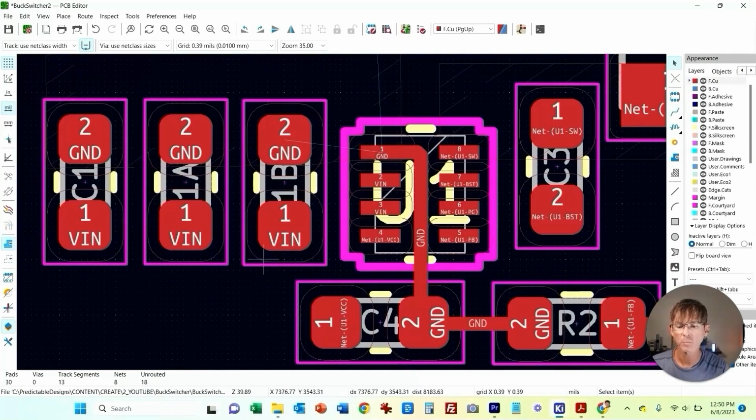Okay, now we just need to place our last copper pour for the VIN, which is going to grab the 3 input capacitors and our input pin here. Keep in mind this does VIN, but this is really the enable pin, which we've just tied to VIN. So this is not critical. There is no current flow through this, so we can just connect with a trace. We'll just tie that to our VIN copper pour.